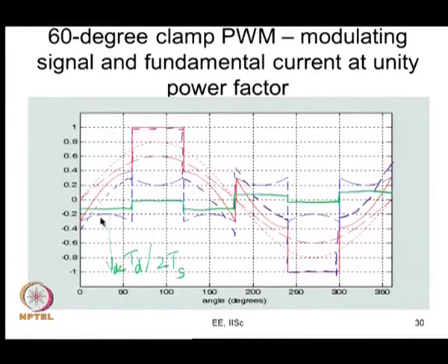This will have third harmonic, ninth harmonic, etc., they will get cancelled off, but this will have fifth harmonic and seventh harmonic, they will get applied across the load. So, the fundamental component of this error voltage, fifth harmonic, seventh harmonic, etc., will get applied onto that, and therefore, there is going to be low frequency distortion as we mentioned before. The main difference between continuous clamp PWM and discontinuous: in all the continuous clamp PWM, you found this error voltage to be a square wave. This V error was constant and it was negative for the positive currents, and it was positive for negative currents, it was a square wave, it was only shifting in phase, but now you see that it sometimes goes to 0 also. That is a significant difference between bus clamping PWM and these ones.